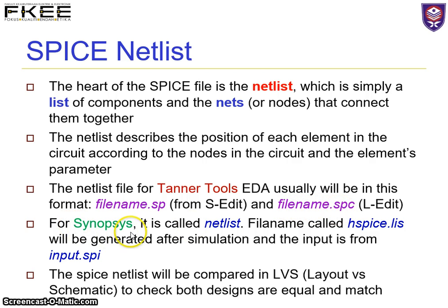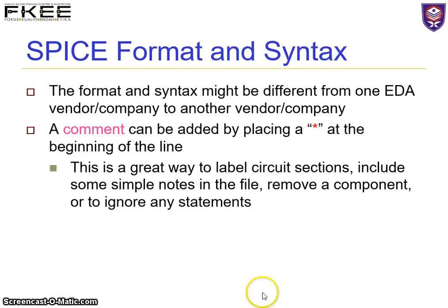For Synopsys, it is just called netlist. Once you have run the simulation, another file will be created, which is hspice.lis, which is generated from the input.sp file. In the LVS, the netlist file will be compared between the schematic and the layout to check whether the designs are equal and match.